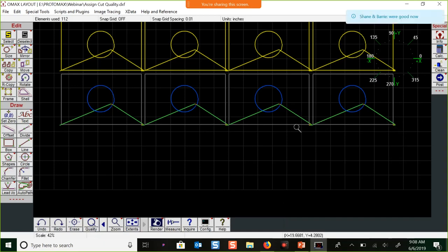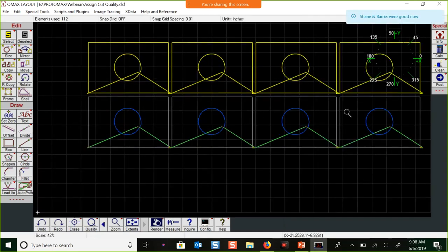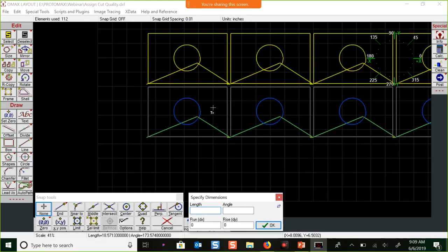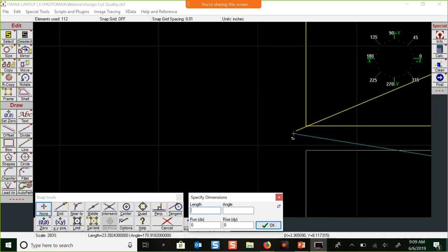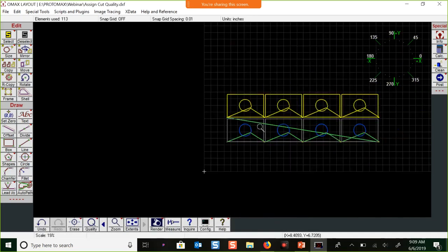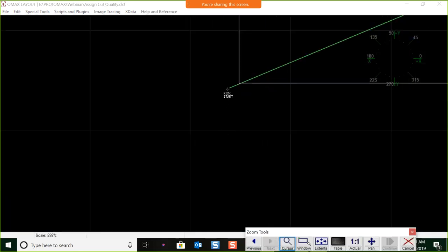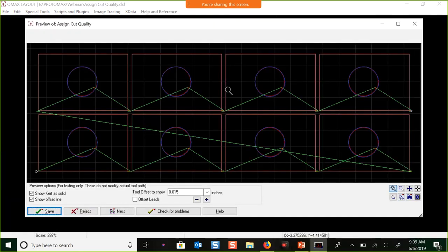Minor difficulties. So again, we have our multiple drawings we've done. Now to connect the two on top, we're going to select line. L is for line, E is for endpoint, and we're going to draw all the way to the starting point of our top level. You connect it to the end, and there it is. If you want more, you can always go 5 at once, 6 at once, and so on. You'll do the same thing to post it. You'll click at the end point of your very first one, and there it goes. It's a quick way to do it.